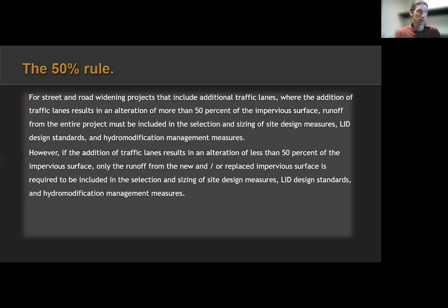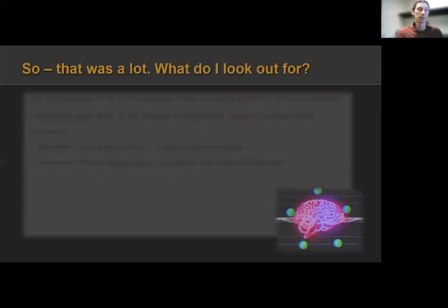Now, for street and road widening projects, the same thing applies. It's very similar wording here. So 50% or more, they need to follow all of the post-construction standards, hydromodification, site design measures, LID design standards, the whole nine yards. But if it results in an alteration of less than 50% of the impervious surface, only the runoff from the new and or replaced impervious surface area is required to be included in the selection and sizing of site design measures. So those are great tools to remember, but that's a lot of information.